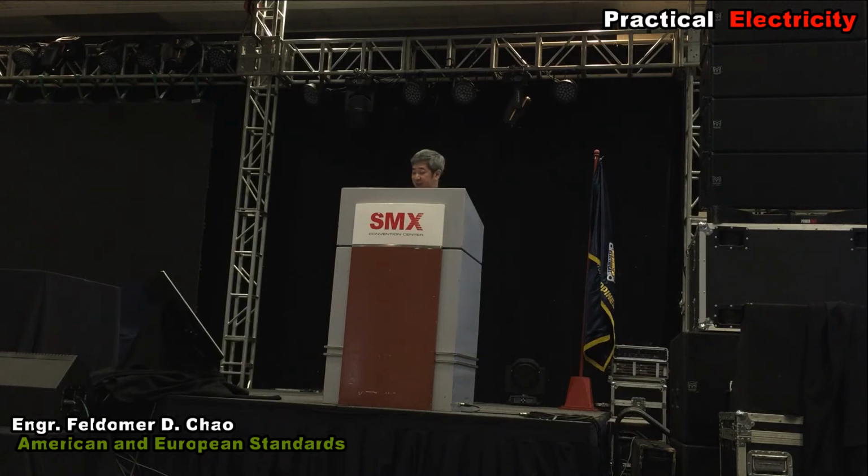They don't have specifications for ultra high voltage. For the American, anything higher than 1100 kV is ultra high voltage. So for the various standards, first and foremost, you have to look at the voltage classification, because that is where the differences between European and American standards come into play.